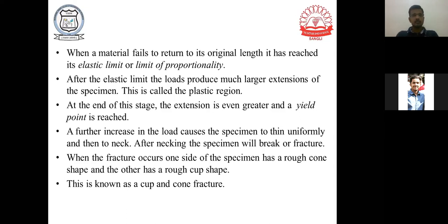This change is permanent now. Okay, still you need not stop there. You go on increasing the load. After a certain time, what will happen? That material will stretch, and after a certain time, one point will come which will end the stretching of that particular material. Okay, and necking of that component, that specimen, will start.